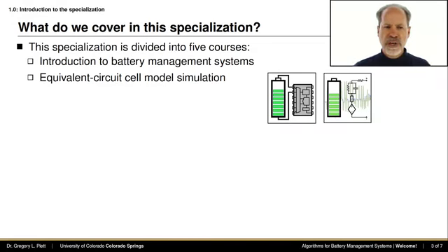In particular, in the second course, you will learn about equivalent circuit models, which are state-of-the-art right now. You will see how to create the models, how to collect data in a laboratory and perform processing to find the parameter values of the models to describe a specific cell of interest, and then how to use the models to simulate behaviors of individual cells as well as large battery packs.